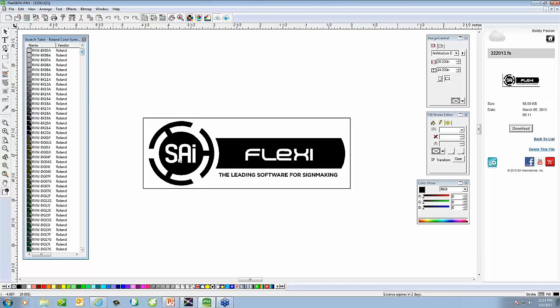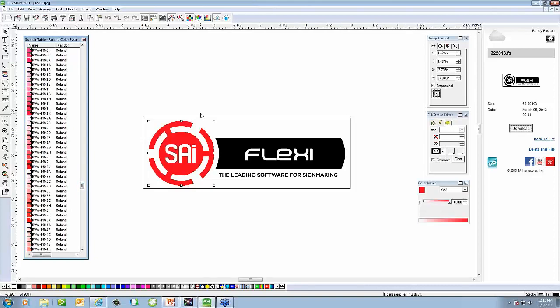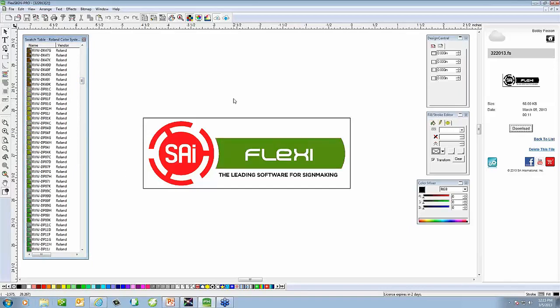But from here, we're going to actually assign, we have basically a complete vector object here. And it's just a matter of selecting the object that you want to work with, and then go from there and choose which color that you want to pick. So from there, based on your vinyl, job, as well as the color chip chart, you're going to scroll through, find the color that you want. And I'm looking for the 42K. And then from there, it's again just picking whichever one that you actually have pulled from that chart. Now, once you actually have these applied, you can then at that point get ready to save the file, possibly archive the file to the web, and then at that point we'll send it out to the VersaWorks.